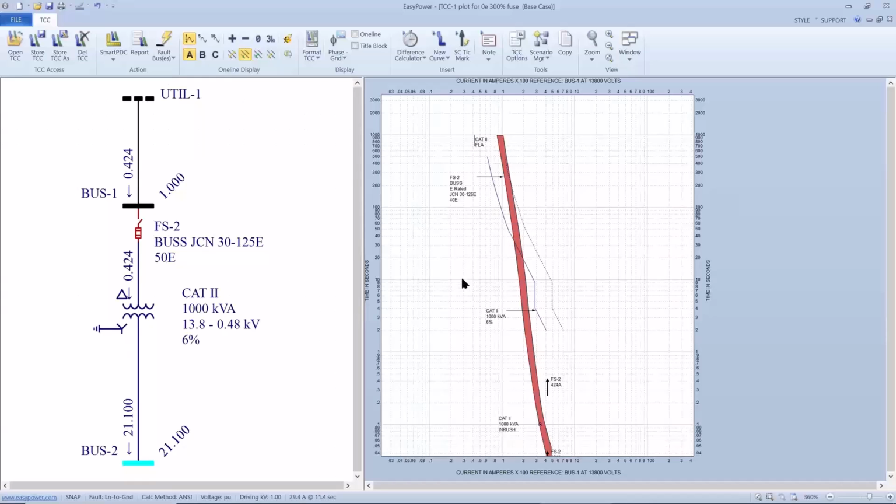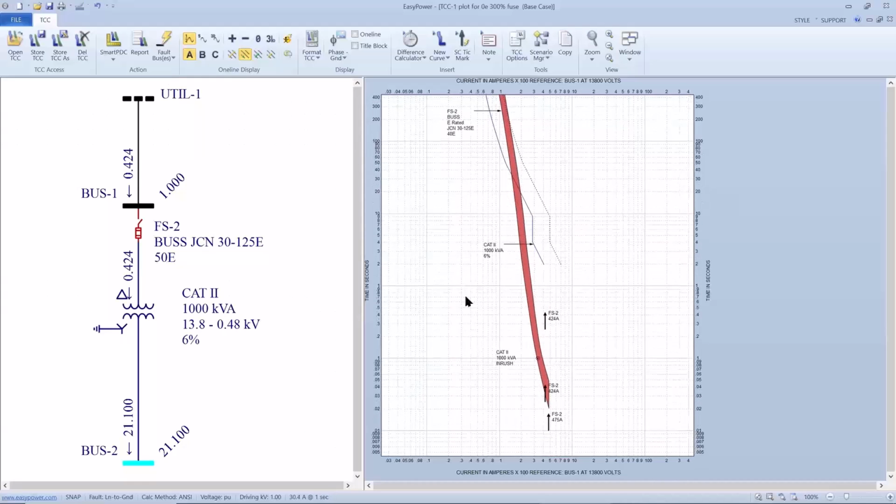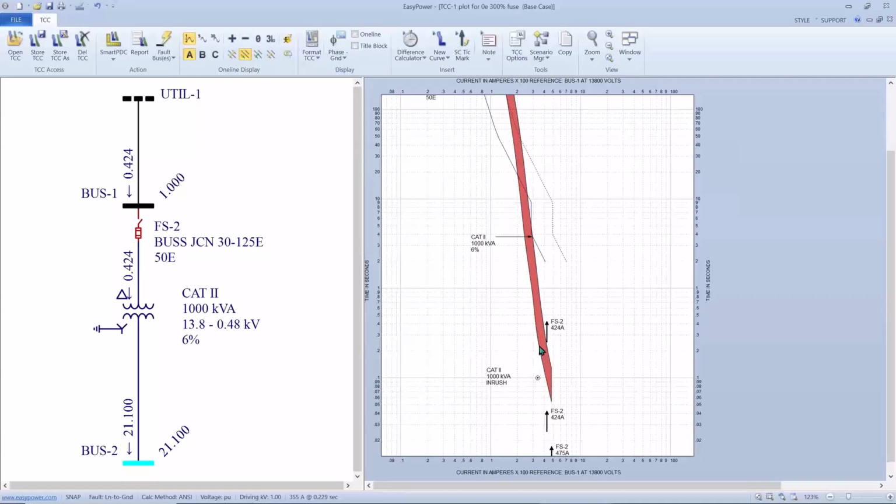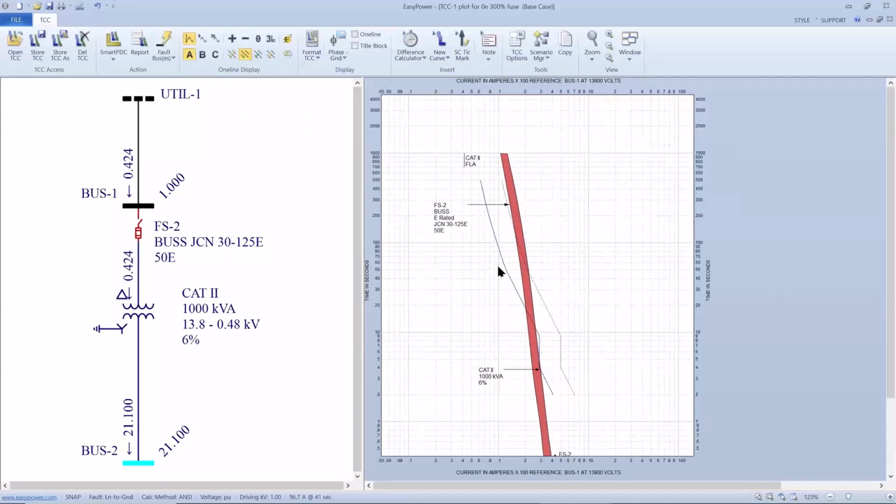Ovide is saying, yeah, Mike is too. How about the inrush? And that's a concern. So I would probably want to take the next larger size, which exposes me even more on my single line to ground fault for these lower currents.